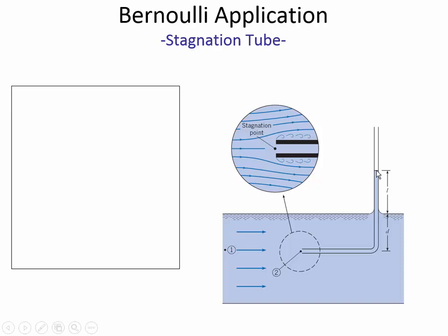So if we start here at the interface of the air and the water, the air pressure is 0. So the liquid pressure here is 0. And of course, we're talking in terms of gauge pressure. As we go down, we could find some pressure in the liquid at this point. But that's different on the inside of the tube than it is at the river, because here at the river, the air and the river are touching, and so they have the same pressure, which is 0.